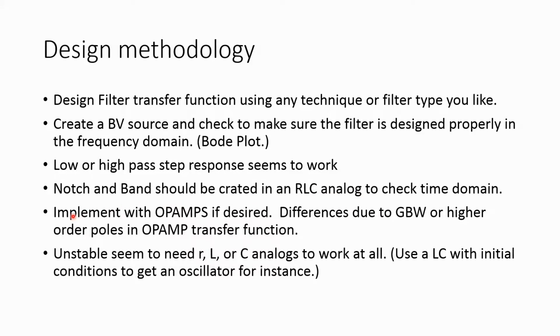Then you would move on to op amps. And then any differences that you see between the RLC analog, meaning it's just a behavioral model using RLC components, any differences you see at that point would be due to the gain bandwidth, or higher order poles in the op amp transfer function, or non-linear non-idealities in the op amp.